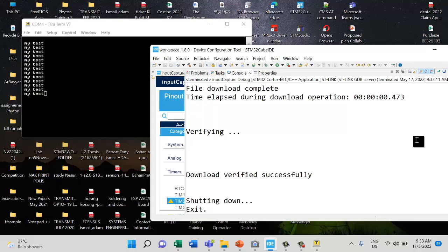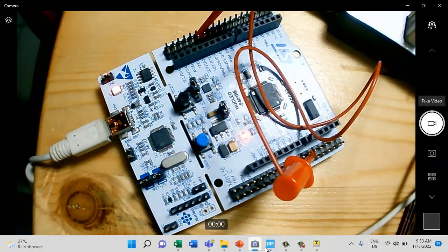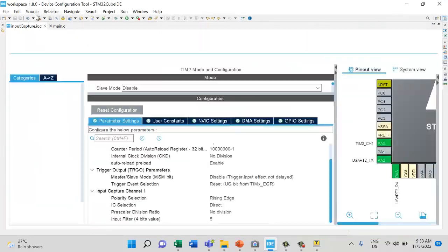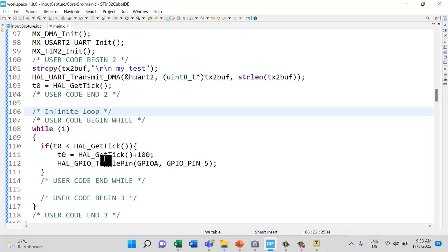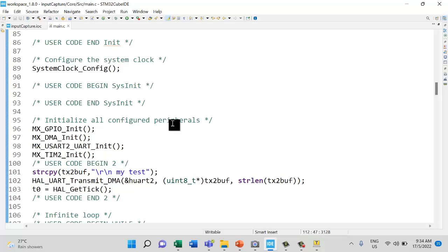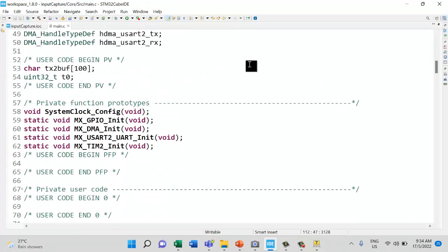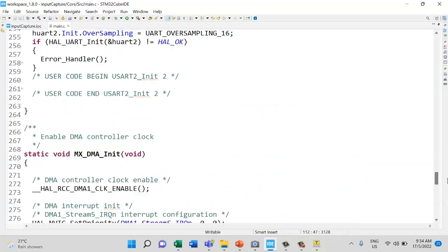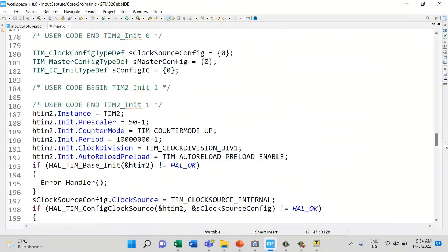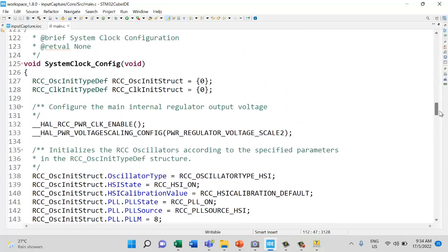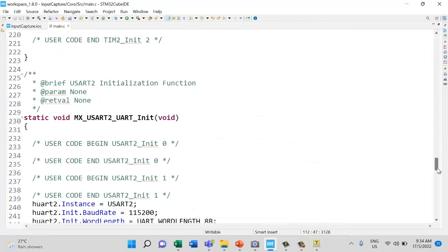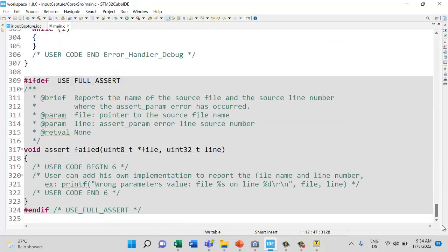And the LED, GPIO 5, should be turned on and off, right? Turn on and off. So something is wrong here. So we check the code. Check the code. Hmm. Check for the GPIO. Where is the GPIO? No GPIO setup here, eh? This one.